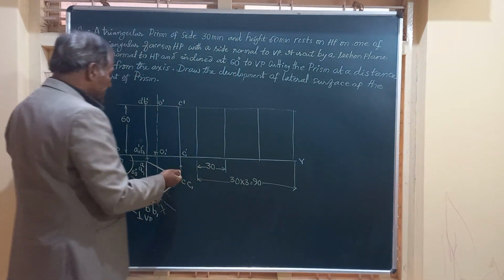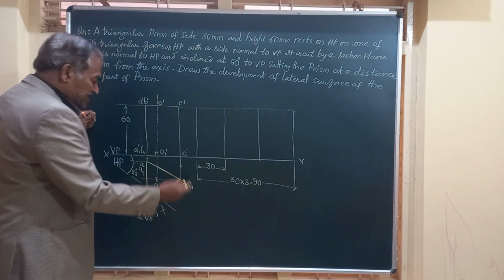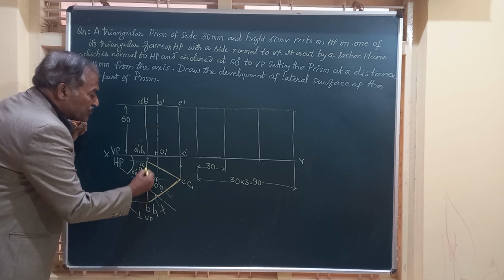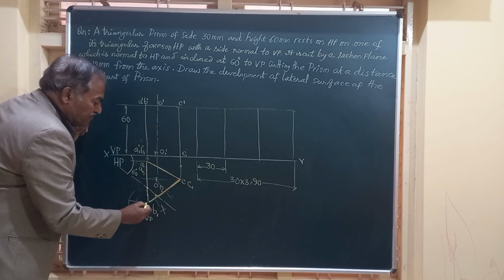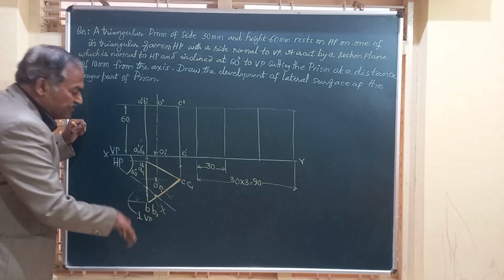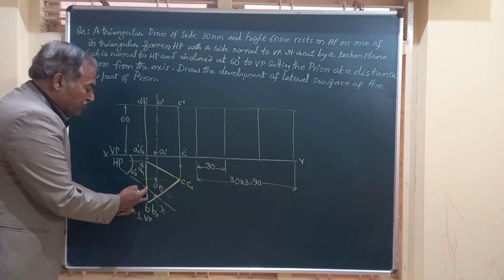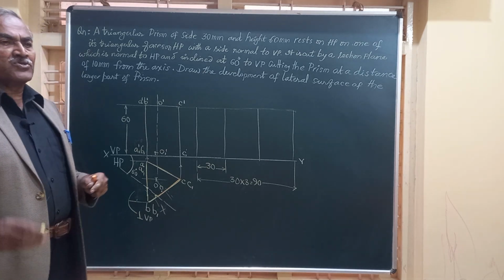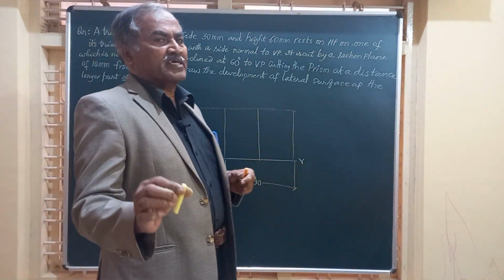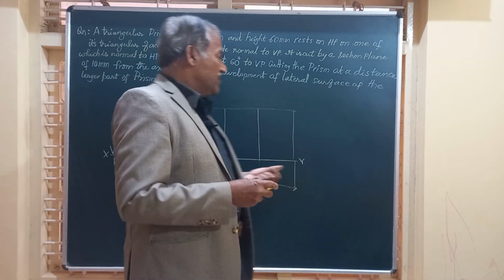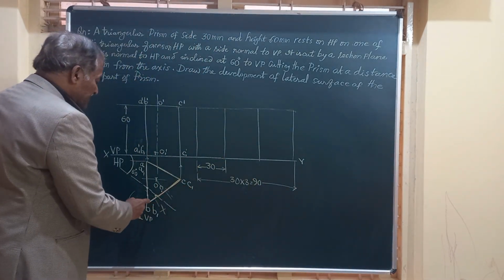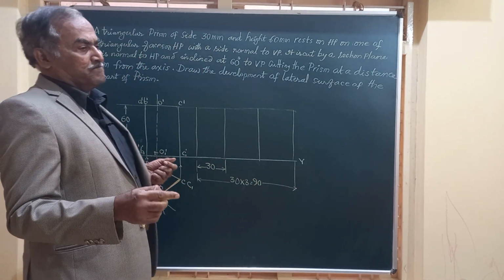Friends, if you observe the top view, you can see here, in the portion retained for the development, the portion BB is thrown out. That is, this vertical edge and this part is not existing. So it is compulsory or it is mandatory to start from the vertical edge BB only.